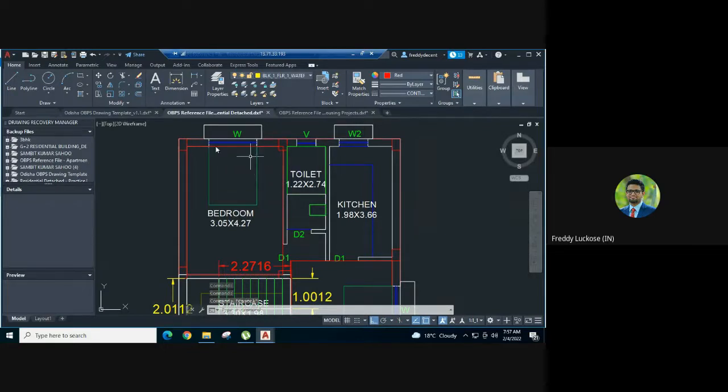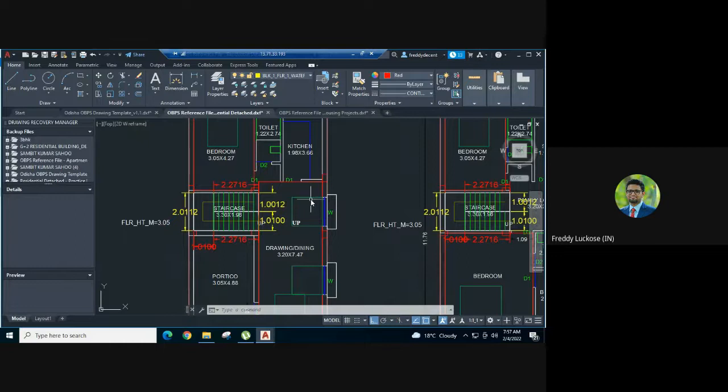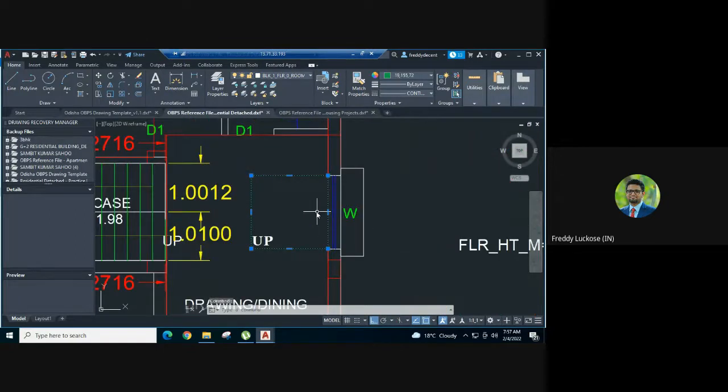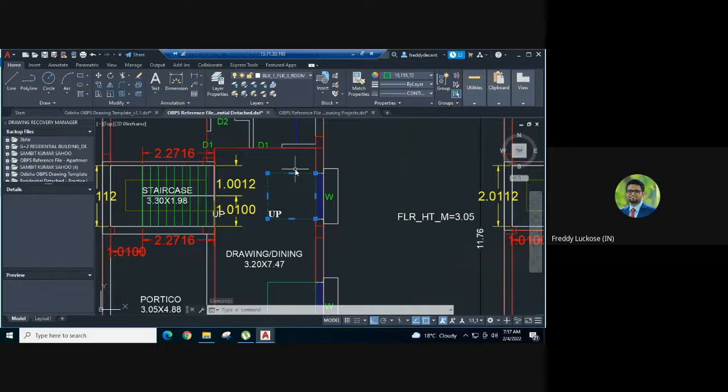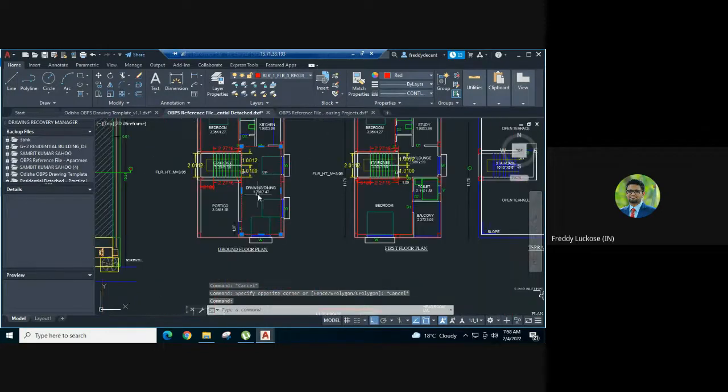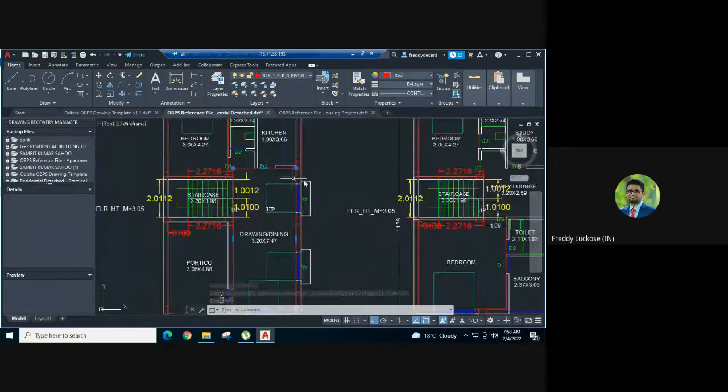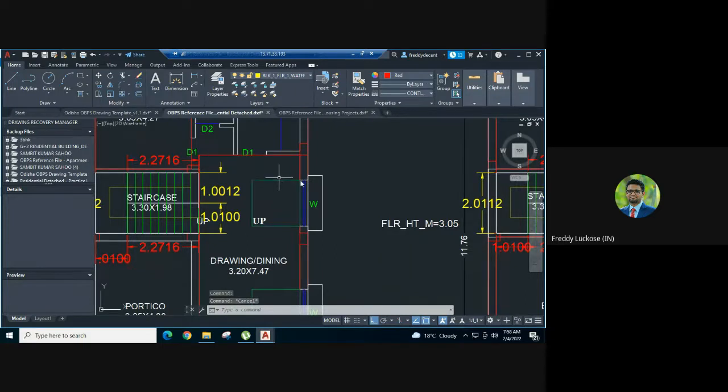As per NBC, the area requirement should be met for each window that is coming inside a habitable room that is naturally ventilated. So for that, you will be making different windows inside the layer called habitable room naturally ventilated. Whenever you are making this polygon for regular rooms such as drawing and dining or bedrooms, you have to make the windows also. And as I mentioned earlier, it is a representation of the area on the floor plan, so you'll be making the width and the height.